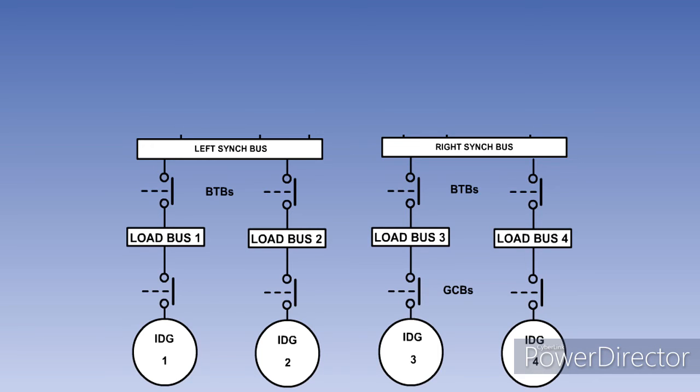All loads are connected to the load busbars. The synchronizing busbars have no loads attached to them. The left and right synchronizing busbars can be connected together by the split system breaker.